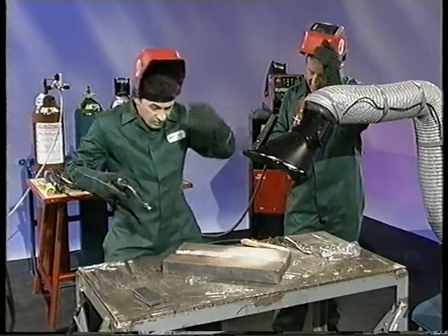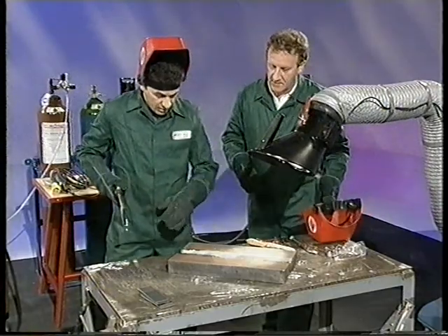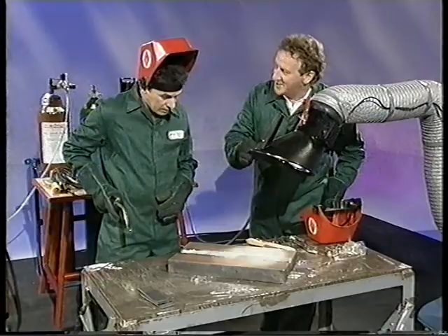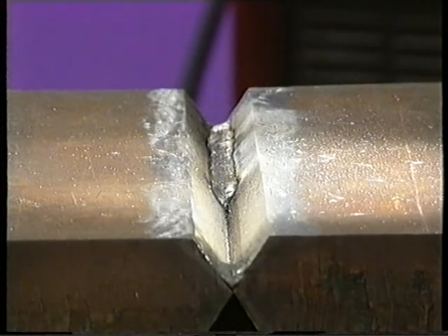Okay, let's see what we have there. I felt very comfortable actually once I got the levels right. Thank you for the guidance there. It's quite a nice spray condition that you get off of these wires, and it is quite a pleasant weld. Now you see that we've got a slag cover on the weld there. We're going to have to remove that.